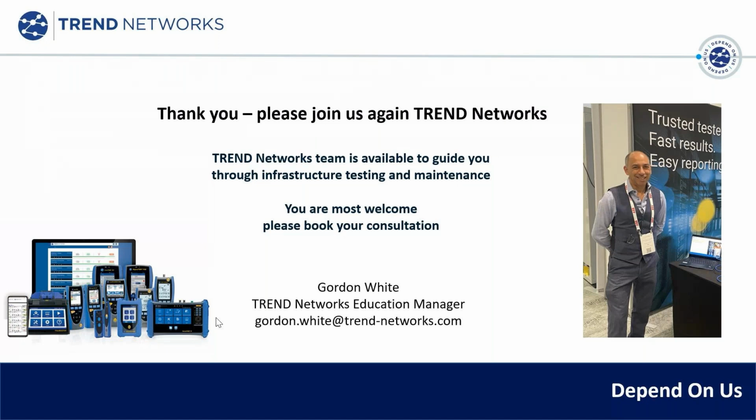So I talked about two elements: DCRU testing for component level testing, and the ability to use a PoE Pro to check will my device deliver enough power. You have the SignalTek 10G. The SignalTek 10G can now put a PoE Pro style test on a link, as well as do a bandwidth test from the end device back through the switch.